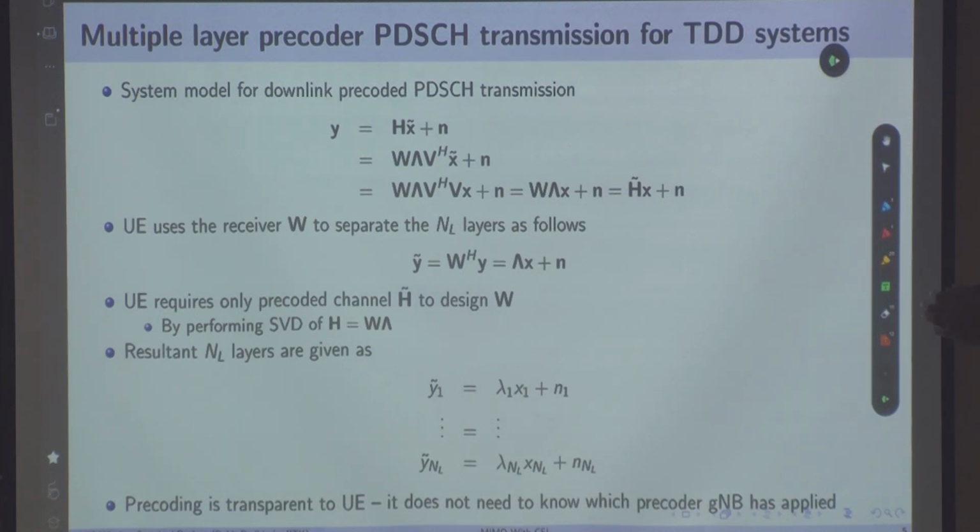So, you will not do the best precoder, you will do some suboptimal precoder which has a lower computational complexity. Then what will happen with this so called suboptimal precoder? The UE will report a lower MCS when this precoder is used by the base station to find out the MCS, because it is suboptimal compared with the SVD based precoder.